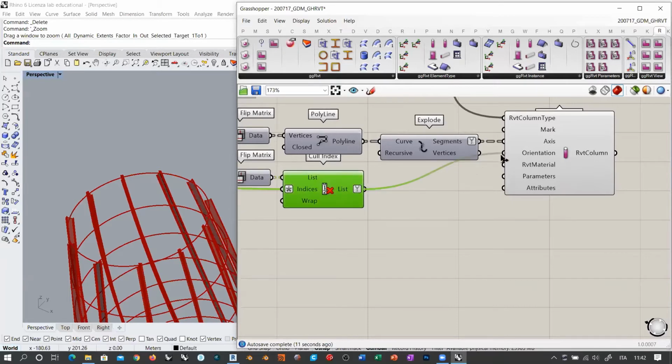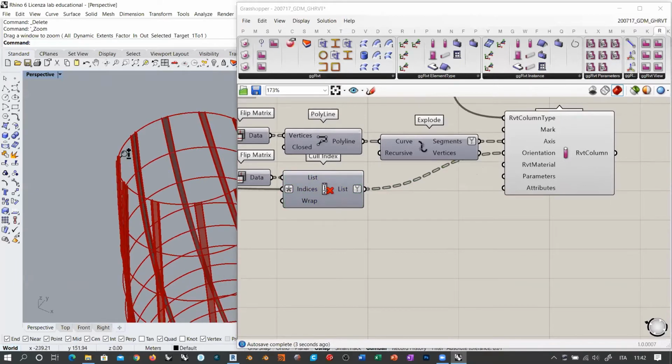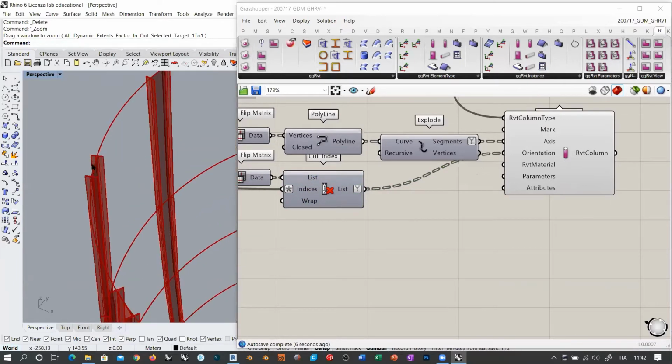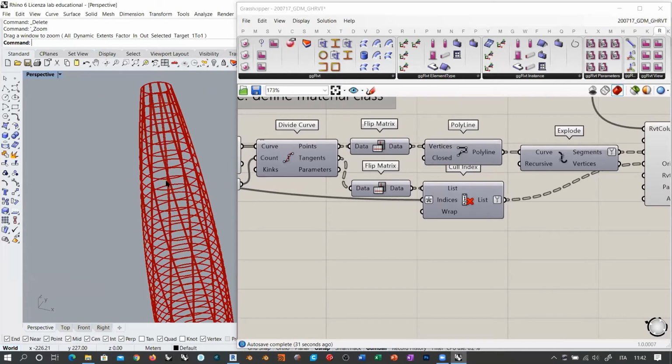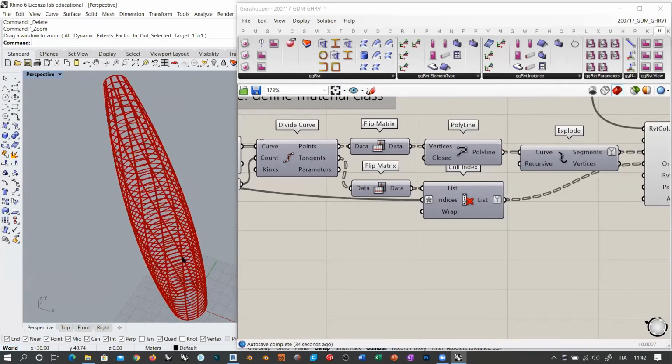So if I do this, now we are orienting this section according to the tangent. So the tangent is becoming the rule for orienting the vertical axis, the y-axis. If you don't want this kind of orientation, it was impossible to see this with a square hollow section, of course. But if you want this to be crossing through the facade, then you must simply rotate these vectors. In this case, you might want to make a simple rotation of 90 degrees, but anyway, it's pretty straightforward.